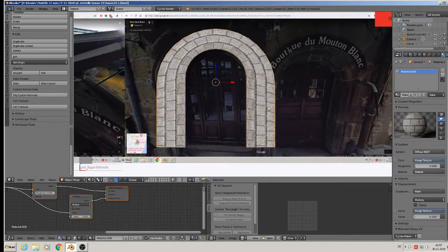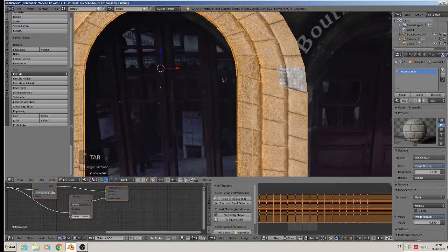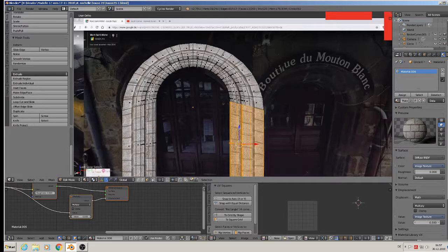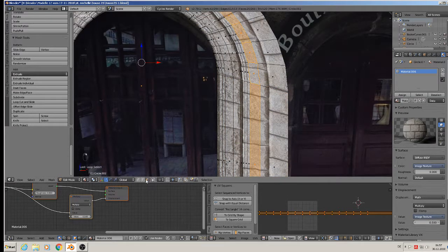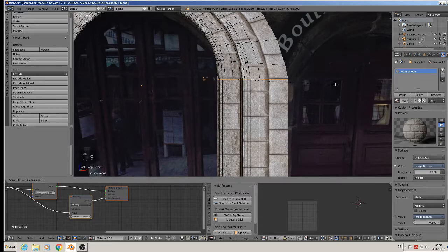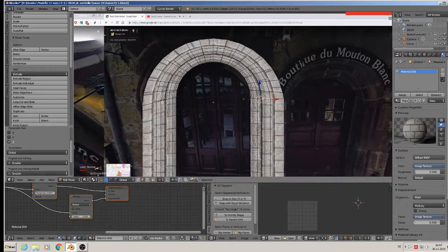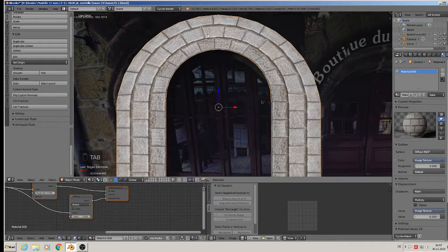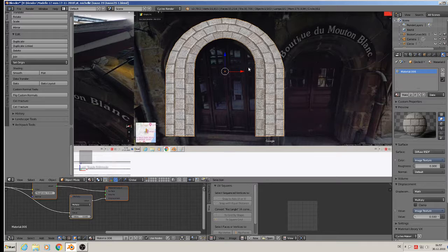Why is it so straight here, you will ask. That is because those lines must be horizontal, and that is the problem there. So we can take a line and scale set 0, then you see it corrects it in straight lines. Rotate, scale set 0. So when you do that with all parts to perfection,